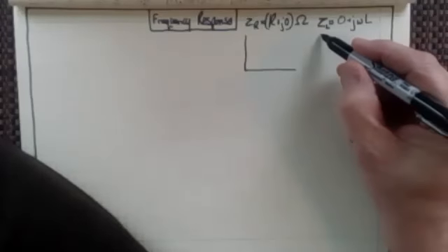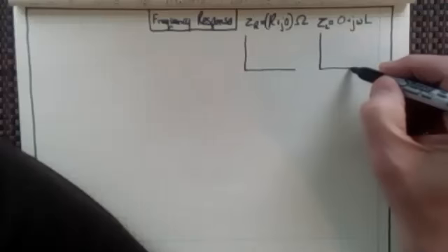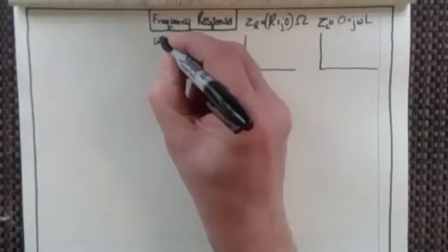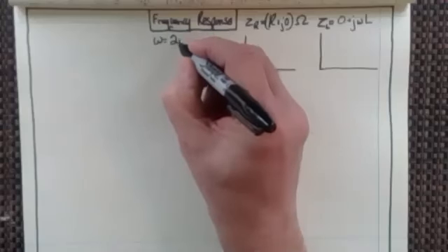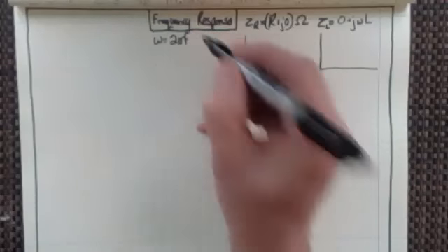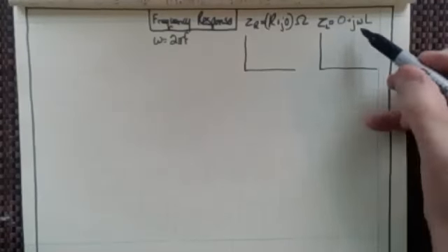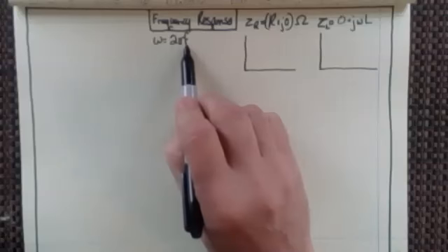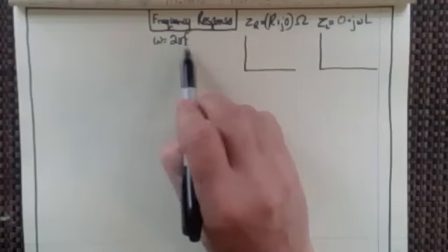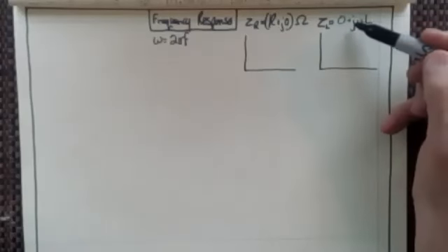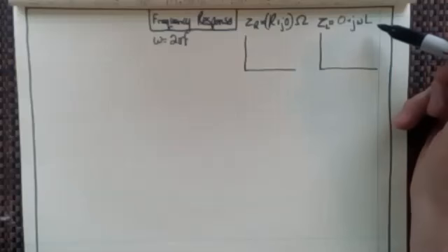And so what would the frequency response for an inductor be? Well, we know that omega equals 2 pi f, right? And so we know that omega is proportional to f. There's no f squared there or anything. There's no omega squared. So it's just omega. So it's just 2 pi f, really. I could have written this as 0 plus j 2 pi f L.